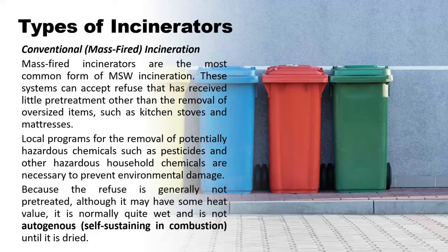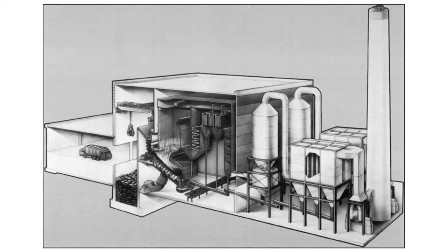Because of the large amount of particulate matter generated in the combustion process, some form of air pollution control device is required. Normally, electrostatic precipitators are chosen. Bulk volume reduction in incinerators is about 90%, thus about 10% of the material still must be carried to a landfill. This is an example of a conventional incinerator.